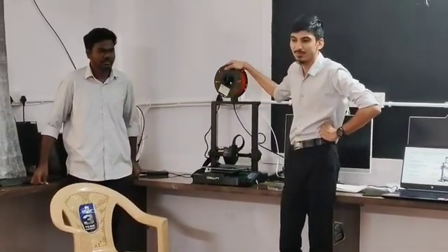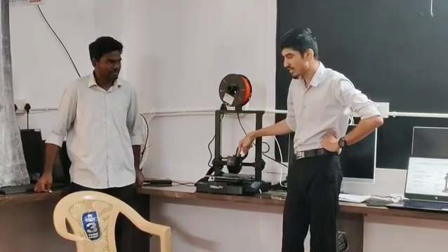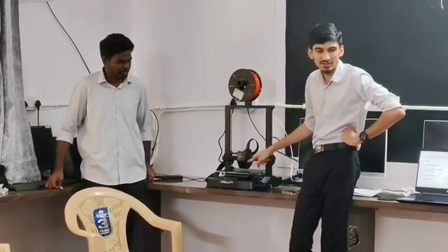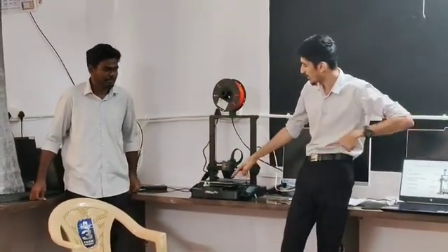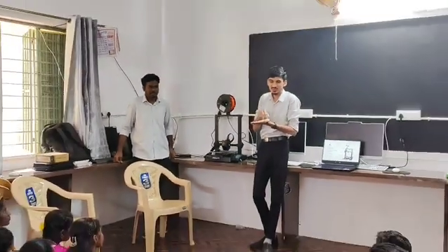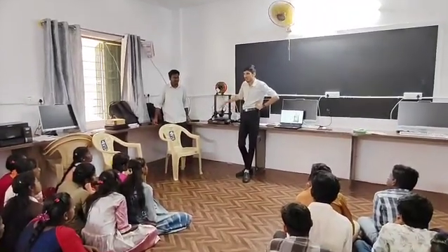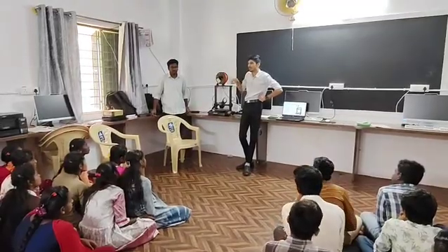This is your material, printing material, PLA. It goes in the cold end, then the hot end. This is the cold end of your extruder. It gets hot here. This will melt that material, PLA material. And from the other side, it will put out the semi-liquid material. When you put it here, it will cool down a little after and solidify. That's how printing goes from a solid, converted to semi-liquid, and then solidifies again. That's how your material becomes whatever design you want.